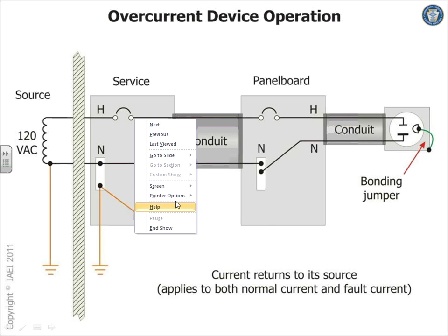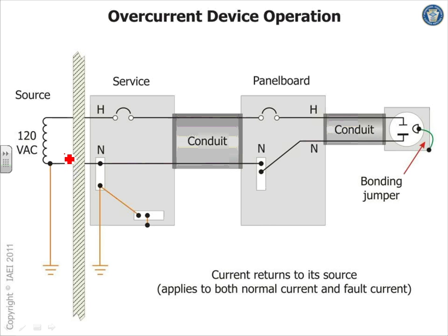I always say people don't understand or miss it. So what happens if you lose a neutral? In a case like this single phase, well, the power will go off, no problem. But if you have a 120/240 split phase power system like we all do, you lose a neutral, you burn homes. If you're not bonded to the neutral, you're bonded to the ground, literally. So that's where we take your neutral and bond it to the ground. Now you stabilize the voltage and you minimize the possibility that a loose neutral will burn your building.